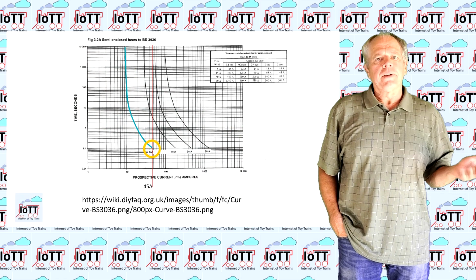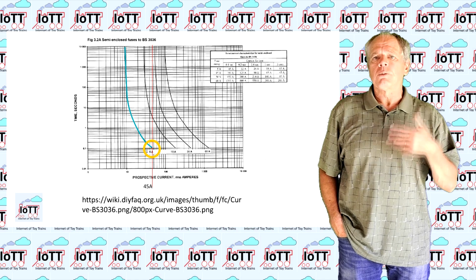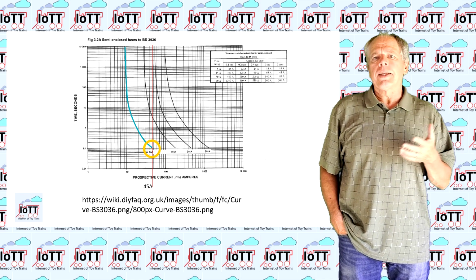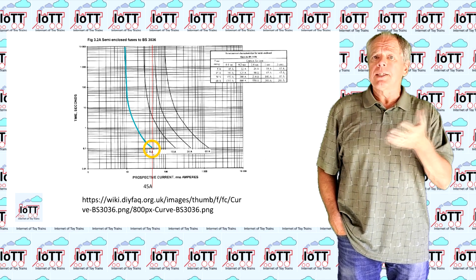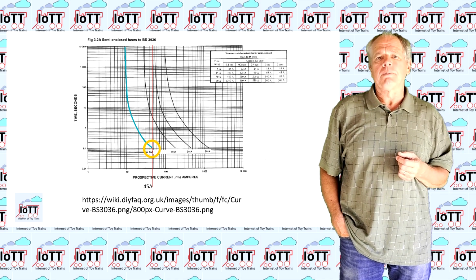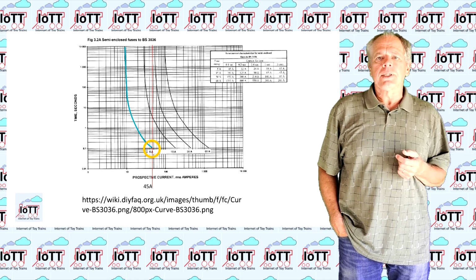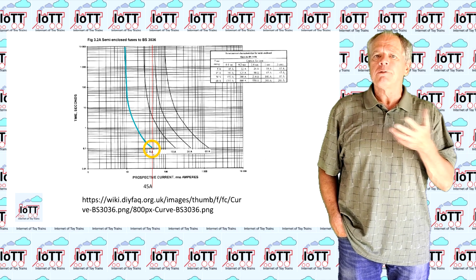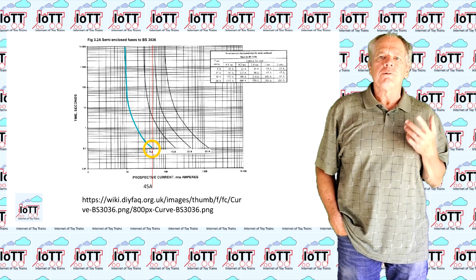interrupted. The reaction time is rather slow, and there are different types of fuses from slow blow to super fast blow. They all have in common that they will break at the given current, but the time it takes is different depending on the blow type. What is important with fuses for analog systems is that the power supply can deliver enough current to make the fuse blow. Here are some typical blow curves of fuses.